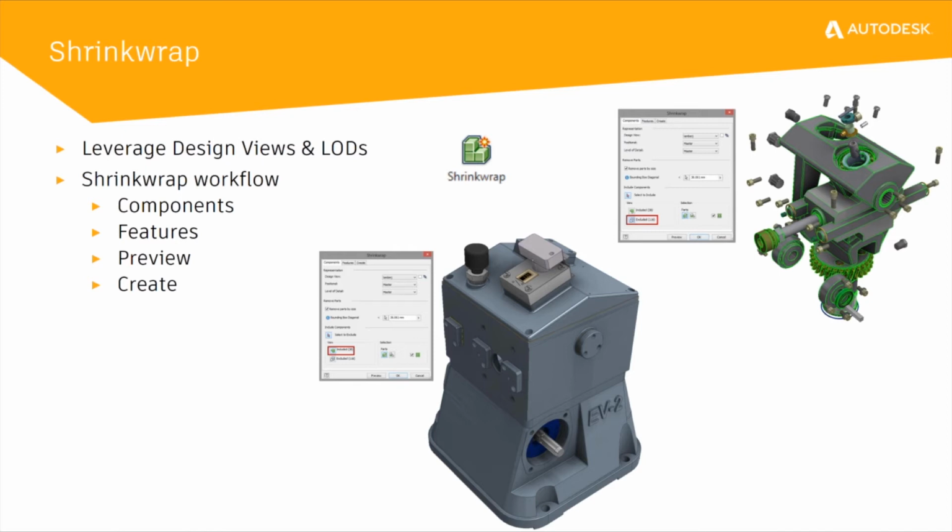So the first thing is you can leverage your existing design views or LODs to help predefine some of the simplification of your model. Inside of the new Shrinkwrap command, you can easily preview components that are going to be included or excluded as part of your simplification. And you can actually even start taking it down from the component level where you can start evaluating features on individual components, whether you want to close gaps, remove features of size, remove parts. And we give users a nice preview all within the assembly environment before you go ahead and create this final Shrinkwrapped model.